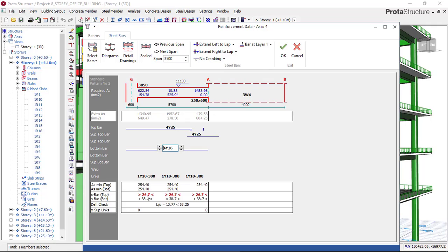So right now I've already explained a lot for you guys. If this place is showing red, once the value is more than 20 millimeter, it is perfectly okay. Right now we are having 26 millimeter because this place shows the chipping size. Like the size of aggregate is 20. So if this place is less than 20, it is not okay. But right now it is perfectly okay.